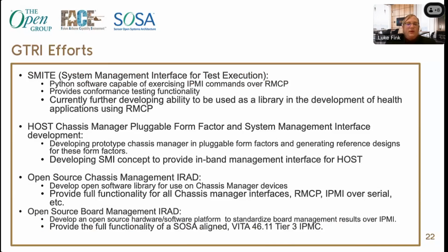So it's a Python software that uses the IPMI over LAN interface to interact with the chassis manager and basically run through each of the messages in IPMI, VITA 46.11 and SOSA specific messages and functionality, to make sure that the chassis manager is responding appropriately to those, and is able to test other IPMCs in the chassis as well.